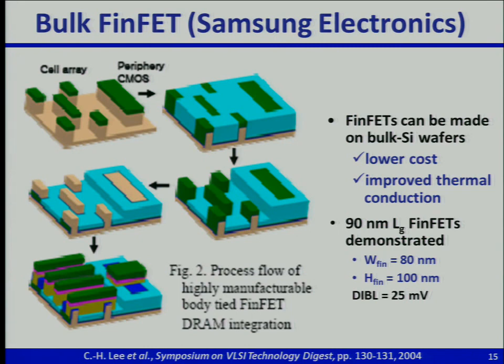Now, normally the circuit designer can draw a wide channel region. Right here, you can make the channel region really wide to conduct a lot of current. Now, for a FinFET, how do you do that? How do you make a FinFET wider? You can make it taller. That makes it harder to manufacture because you have this narrow thing, and you have to etch vertical sidewalls, and it's going to be a huge aspect ratio.